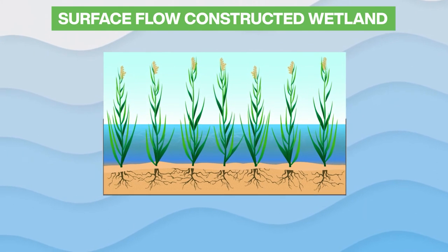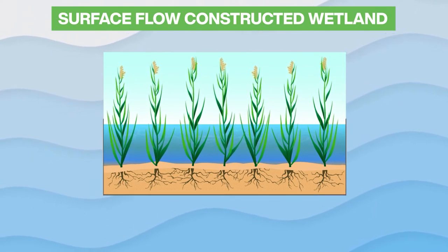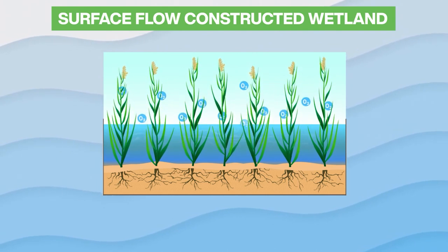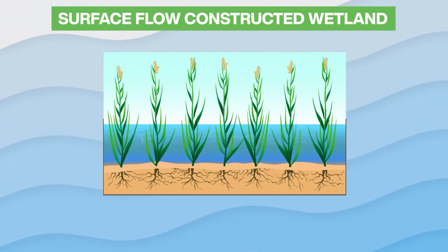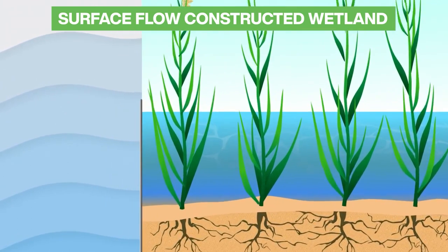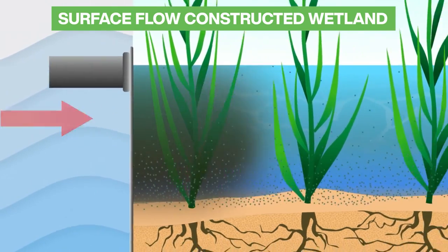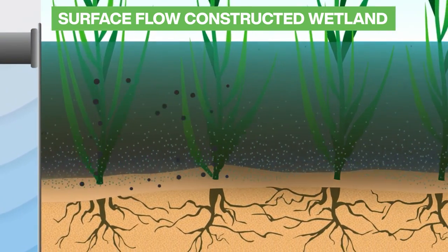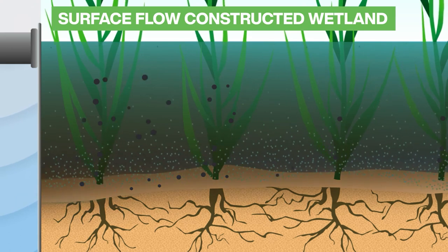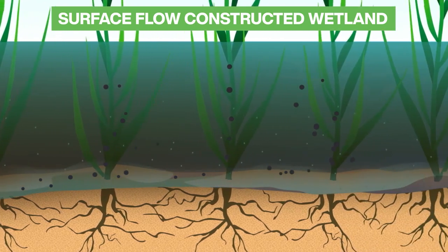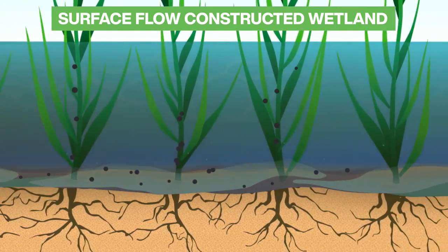The distinct features include: first, aeration via an open water surface; second, the formation of silt through the sedimentation of the suspended materials at the bottom; and third, filtration, which is performed with plant stems rather than sand and gravel used in other types of constructed wetlands.